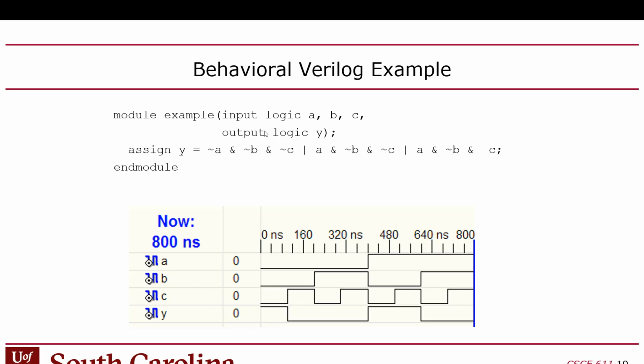And we're going to tell the tools that we're using a 50 megahertz clock. So if it's not able to make your CPU meet that timing constraint, you will get an error. It'll tell you that. You'll get a timing violation. But 50 megahertz is so slow that even in this class, without any kind of optimization, we can easily make that timing constraint on these FPGAs.